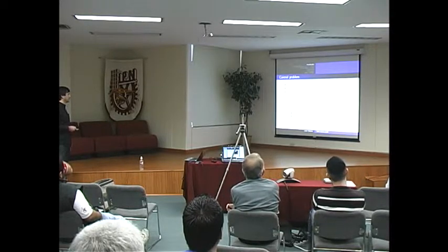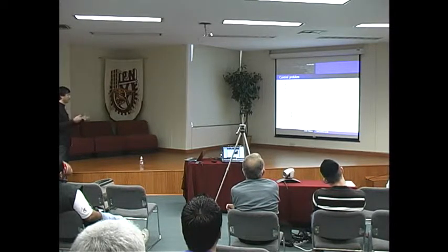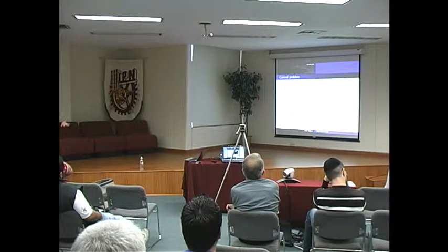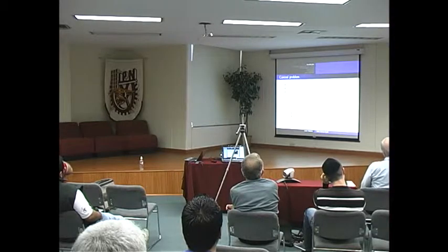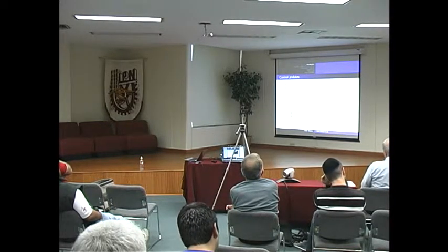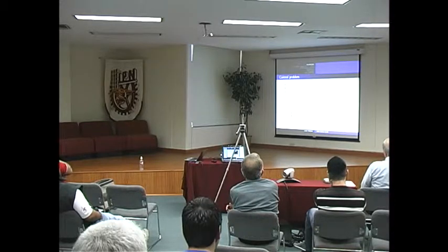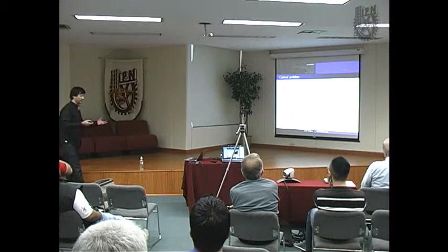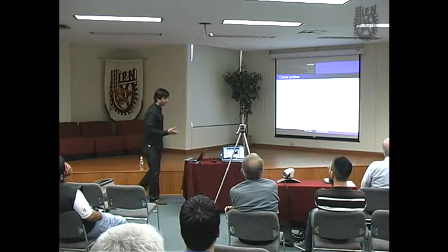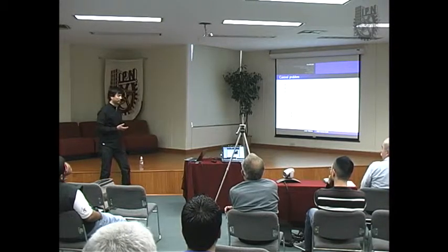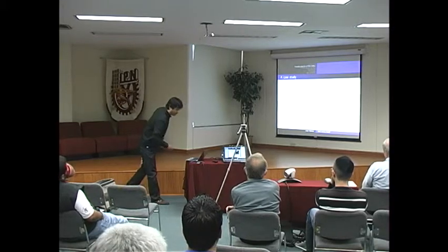Here is a diagram explaining the control problem. We have here feedback of the output voltage, and then we have the controller, and between the controller and the boost converter we have a nonlinear saturation function, which we introduce, and it complicates the problem for stability.